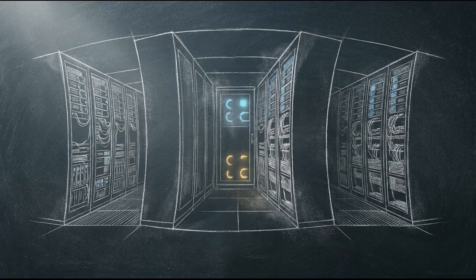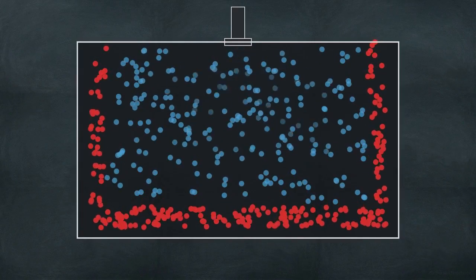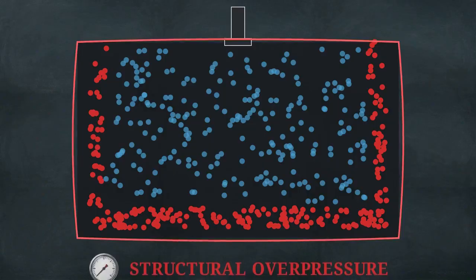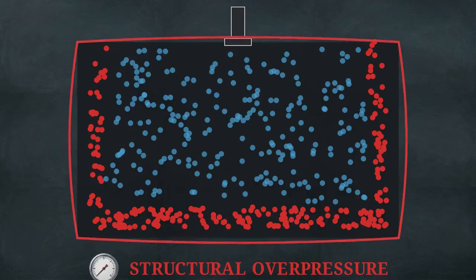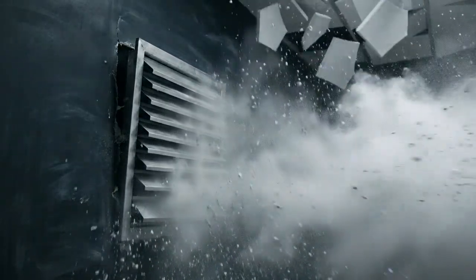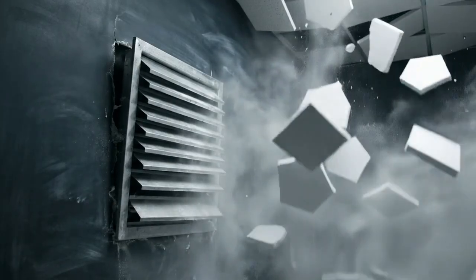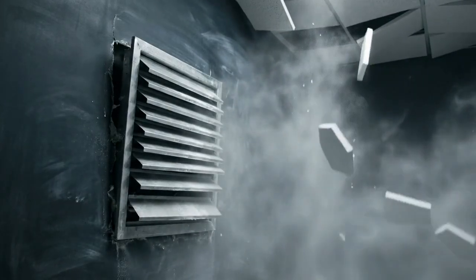Delivering this much mass into a sealed room creates extreme structural pressurization. Injecting 205 cylinders of gas in 120 seconds rapidly compresses the existing air inside the enclosure. Without mitigation, this overpressure will blow out ceiling tiles, buckle partition walls, and destroy doors. Preventing structural collapse requires massive, precisely calculated dynamic pressure venting.